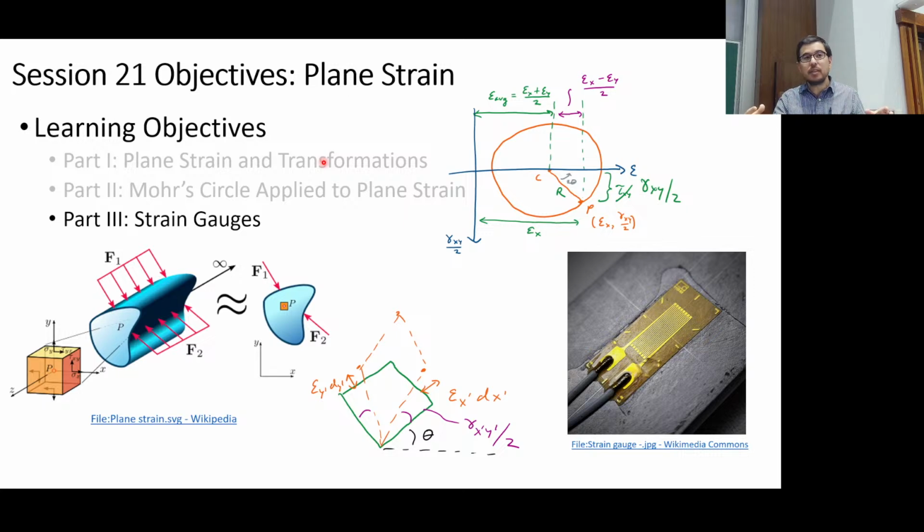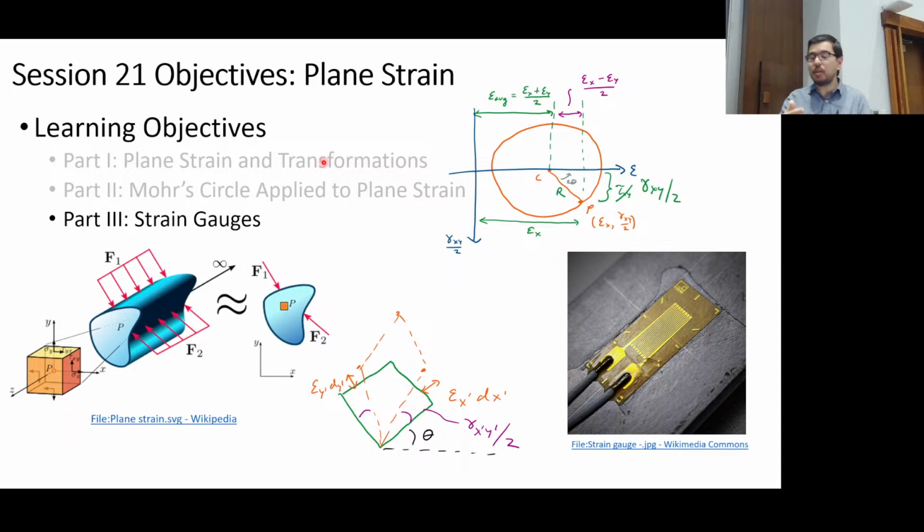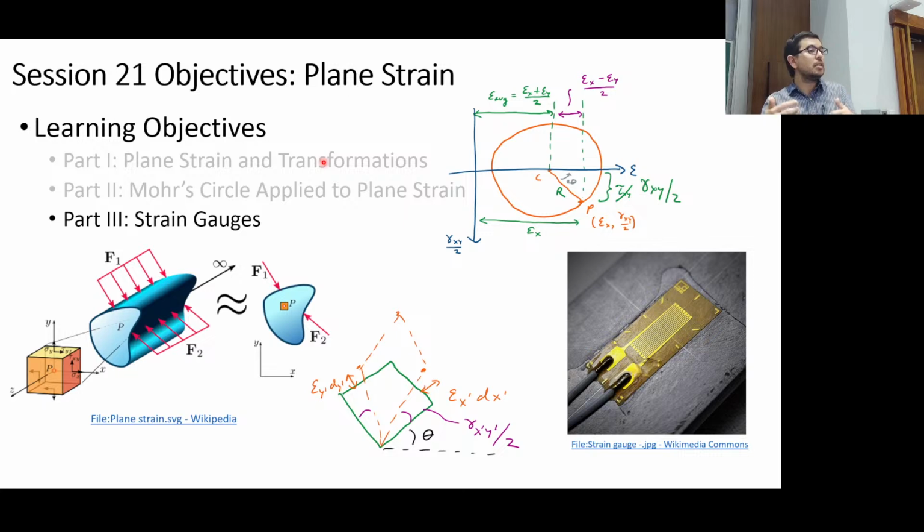Throughout materials. But it turns out there's another case that you'll talk about next semester when you take design of mechanical components. In corners, often you also have high stress concentrations, mostly for vibration and impact loading, and those situations are also at the surfaces. Okay, so it's kind of nice that strain gauges go on the surfaces. It's like this nice, beautiful thing that we can put the strain gauges where the most likely problems are going to be.